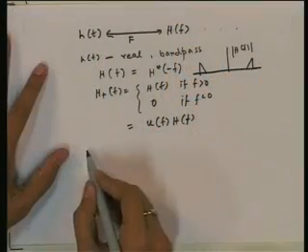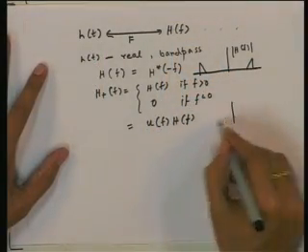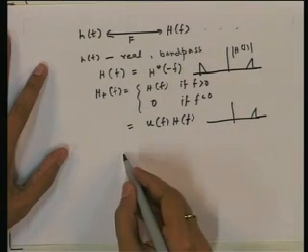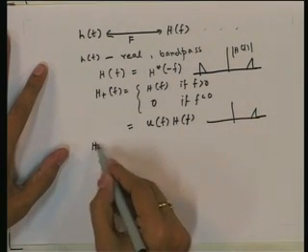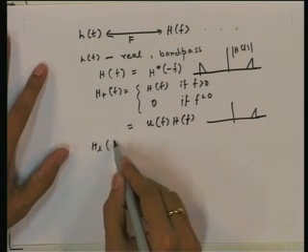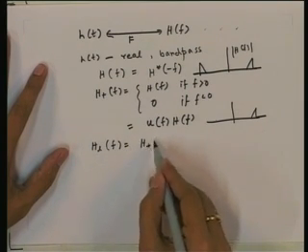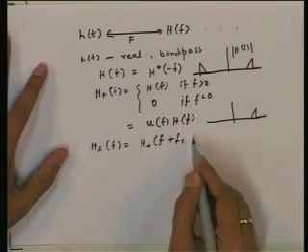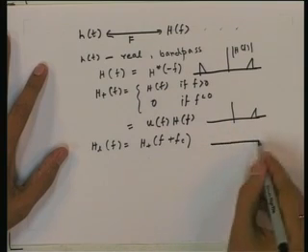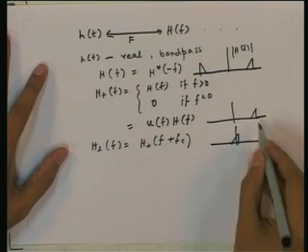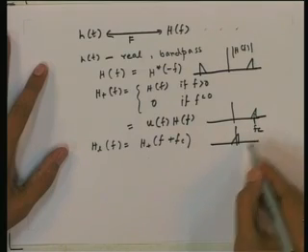Okay. Again, similarly this is missing a scaling, which we will neglect for the time being, and later we will explain why we have done this. And again, just like bandpass signals, we will shift this, so this is basically only one side, H plus of f. Now H_L(f) is H plus of f plus fc. So you basically shift it here. This spectrum is now such that this fc is brought to 0.